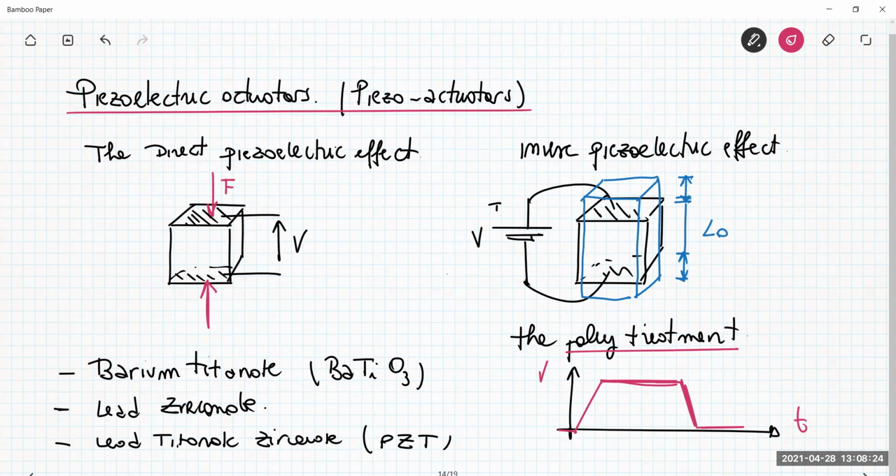Because if you apply a negative voltage to the same material, then the negative voltage can have what is called a depoling effect, so it acts to reduce the piezoelectric activity. So this poling treatment is performed by applying only positive voltage, because negative voltage can have an adverse effect, but we have to say that sometimes this is not true. For the rest of my discussion, suppose that this kind of device can only accept positive voltage for enhancing their properties and for getting the piezoelectric effect. But anyway, these are the main characteristics.